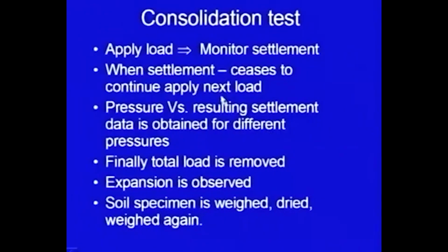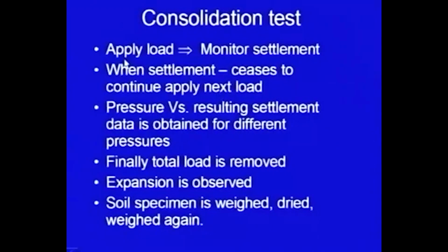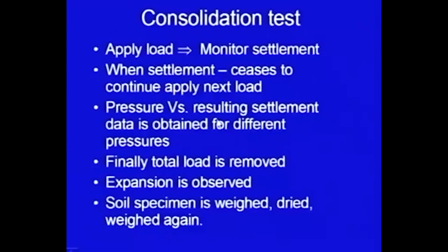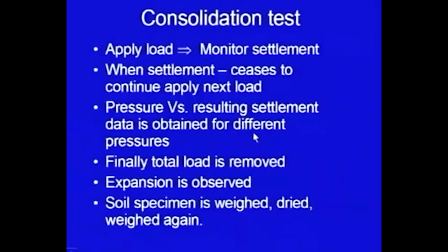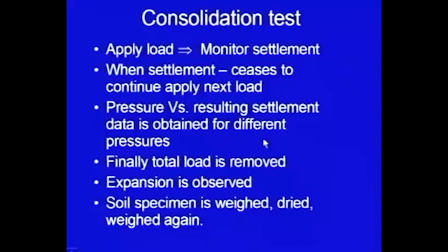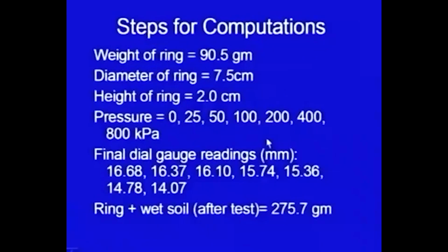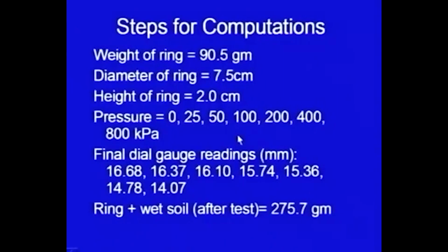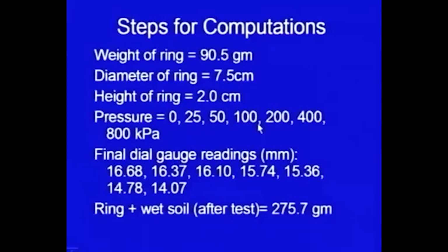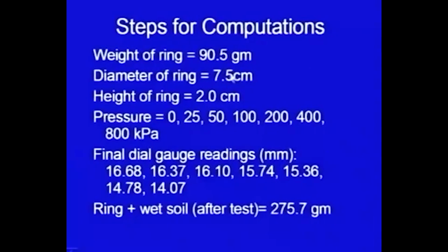In this test, as we discussed last time, you apply the load and then take the readings. Ultimately, we apply different pressures, and corresponding to those pressures we find out the settlements. Today let us go to the computations. Here I am discussing only one method. There are more than one method available in the books you might have studied. Let me take an example.